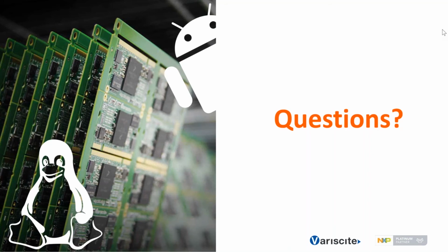In that regard, there are other solutions that might come even from previous i.MX 6 ULL in a kind of single core, but with a lot of interfaces integrated inside. It is very power efficient as well, again, if you don't need the performance of dual or quad core or more multimedia features inside. So the entry level, I would say, will be the 6 ULL for very efficient power consumption. Then above that, you will go with the Nano or the Mini with the 40 nanometer design that is integrated within the silicon node itself.